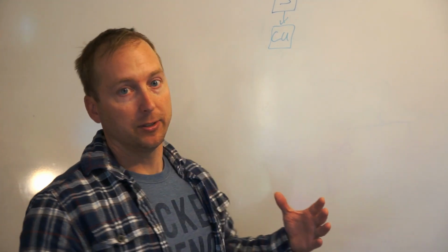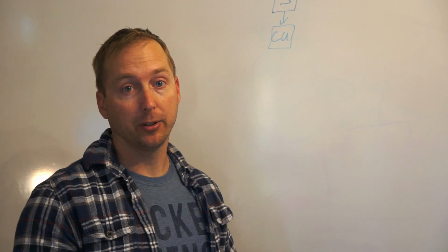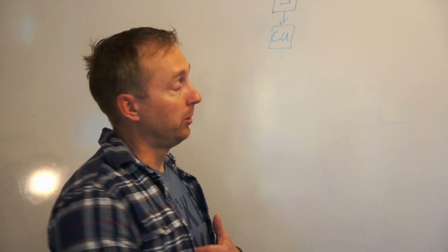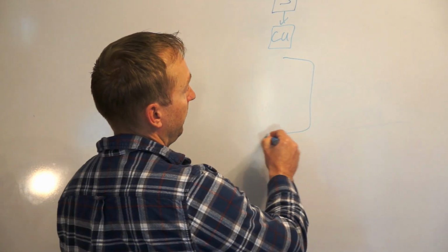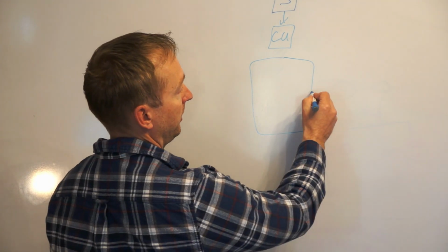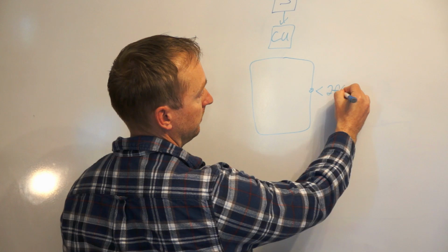For this instance, since we only want to move forward and not run into any objects, we will run a simple loop. This loop will constantly go around, and it gets to a point and it says, are we less than 2 feet?